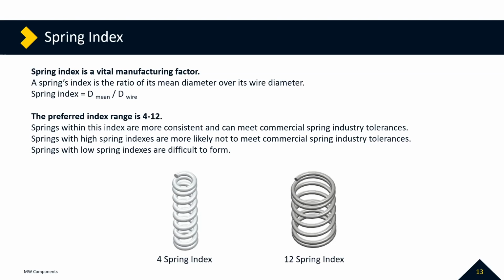It can be made, but anything upwards of around 10 to 12, you start to get into whether or not it can be manufactured from the standpoint of clearance issues with maybe a pitch tool versus a cutoff. It's potentially going to have some issues with interference as well. But then also your tolerance level.